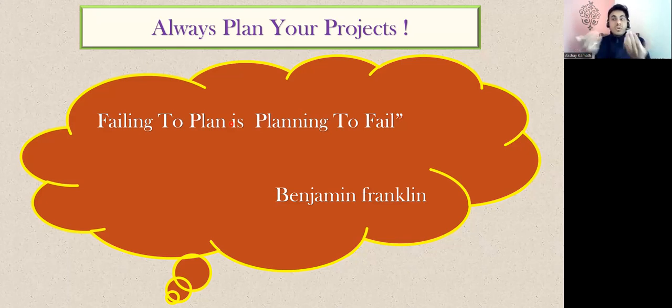Now let us say you took a project and you didn't plan all these things, like per day how many footings you are going to do the excavation for, after how many days of excavation you are going to do the PCC, after how many days of PCC you are going to do the footing reinforcement. If you don't plan which footing has to be done on which day, and you try to execute everything at once, later you will be in trouble. So always you have to plan a project.